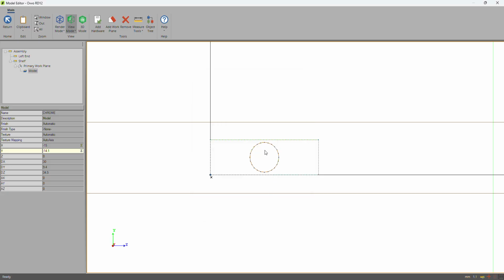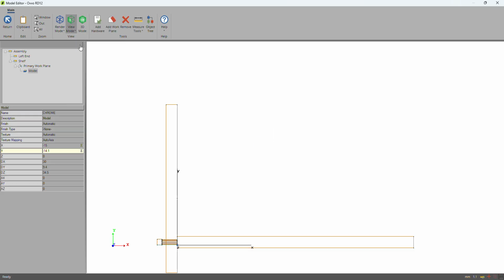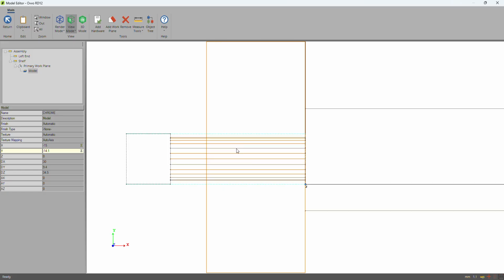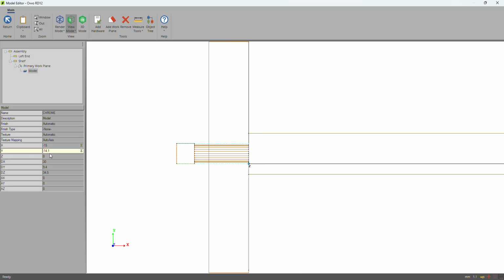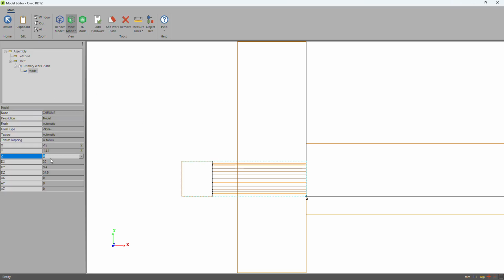All right. Then we can go just here to 3D mode, to view mode front, so we can see it from the side. Now, I want this whole piece here to be inside into the side here. So the way we do that is we work with the Z value here. So I'm just going to check the value and I'm going to see, okay, so that is 26, I think. So the Z value doesn't need an equation. There we could just go and say minus 26.